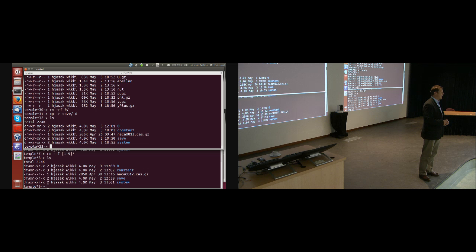And for the people who are advanced, among the tutorials there is one called engine cooling. What I need you to do is to convert the Star-CD mesh and run the simulation. When you're finished, create a scalarTransportFoam case and run a transient simulation tracking the scalar from the inlet to the outlet to find out how the domain is filling. And if you're really advanced, then show me how to calculate the residence time as well. That will keep you amused for a couple of hours, and in the end we will do it quickly.